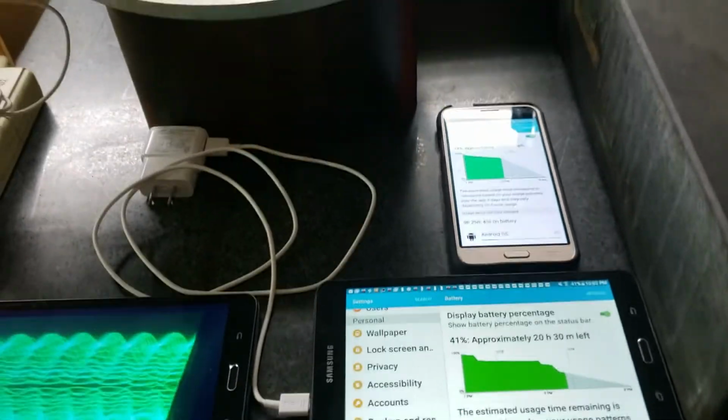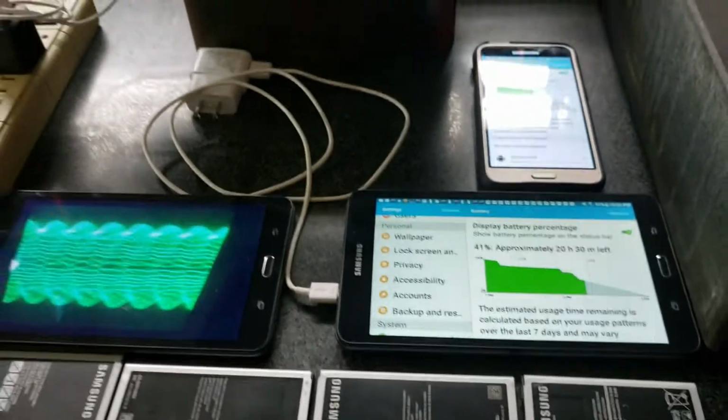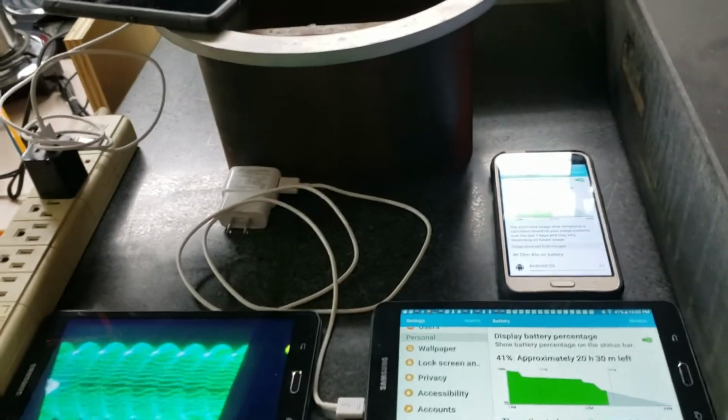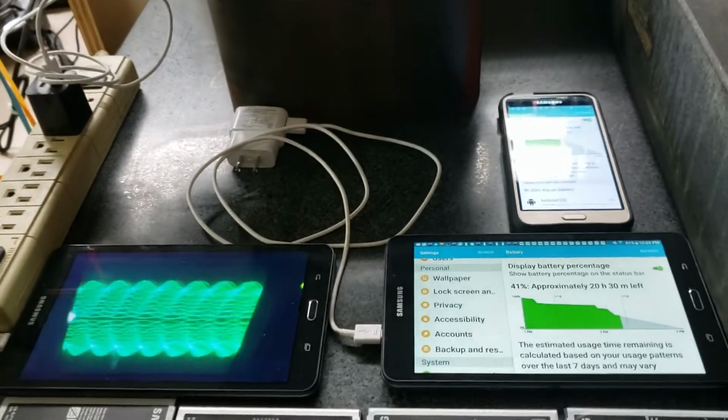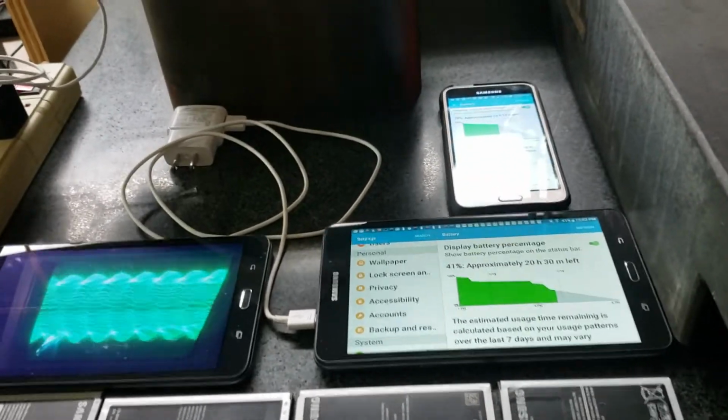I'm on top of a piece of metal plate, on top of a granite block, so that we have an even temperature distribution, and it's been sitting like this all day long, and everything's been running all day long for at least 10 hours. So we know we have a very accurate heat soak. Then I'm on top of this piece of ceramic that can easily handle 10,000 degrees.